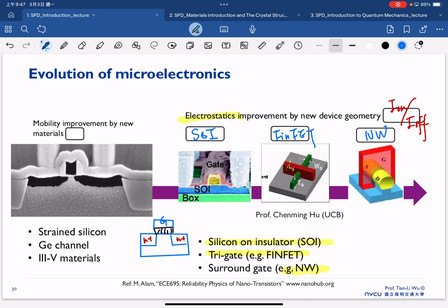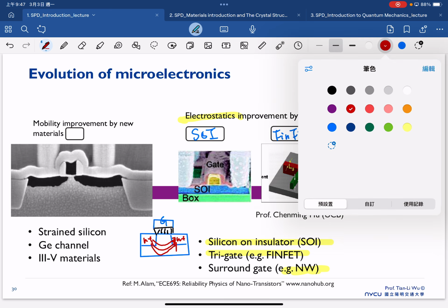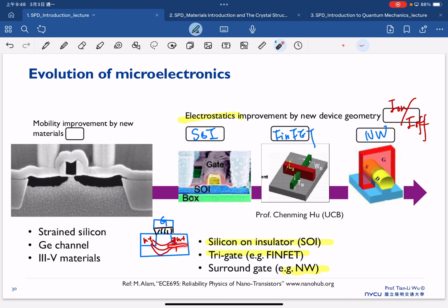So as we already illustrated, one of the main reasons for high off-state leakage current is that the carriers tunnel through the substrate and reach the source side. That's why we have the high off-state leakage current. And the simplest way to try to eliminate this off-state leakage current is to replace the substrate. This is usually what we call a conducting substrate. Conducting means that this is a material in which electrons and holes can conduct.